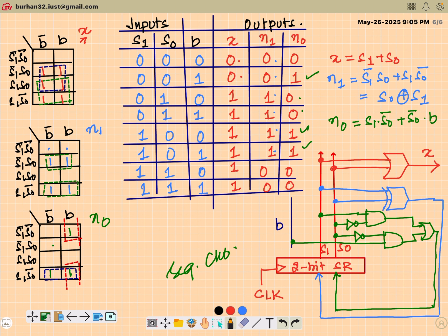Fine. We'll take some practical examples, some designs that are a part of your curriculum, and we will design them using the FSM approach rather than design them directly. We use the same approach as in the combinational circuits. I told you that in this course, we will follow the designer's approach rather than simply analyzing. Right? So we'll come up with design problems, capture their finite state machines, and ultimately following this methodology, try to implement them.